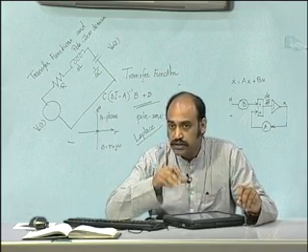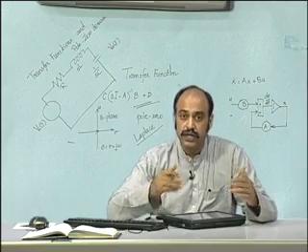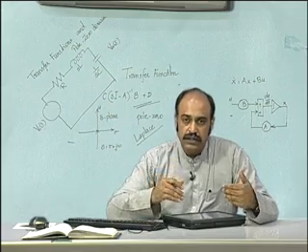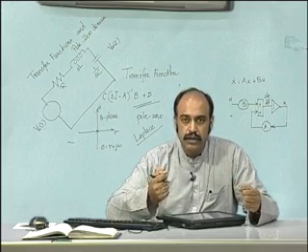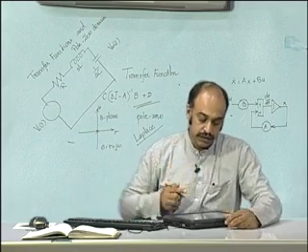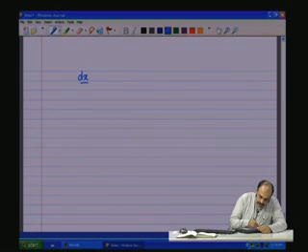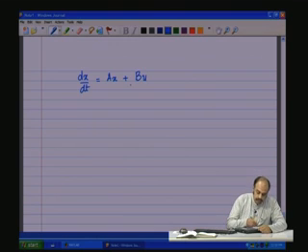Likewise, for the transfer function, because transfer function is under the constraint that there are no initial conditions, because state space has no such restriction, a transfer function should also be obtainable from the basic state equation. So, the state equation in the general form, we see that it is dx by dt equals Ax plus Bu. This is the dynamic equation, and the output equation is given by y equals Cx plus Du.